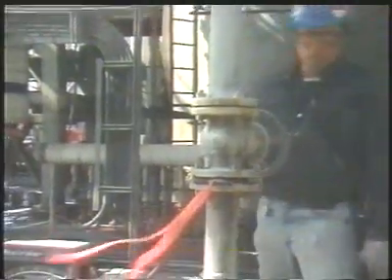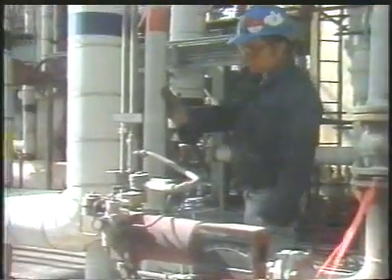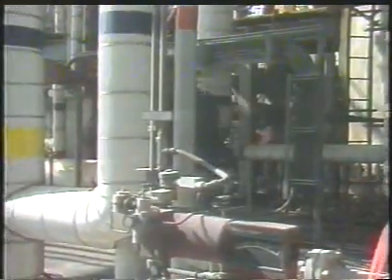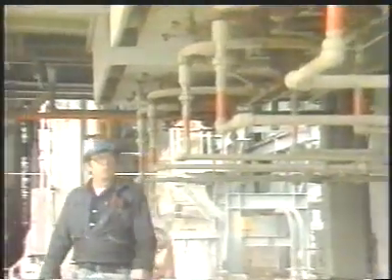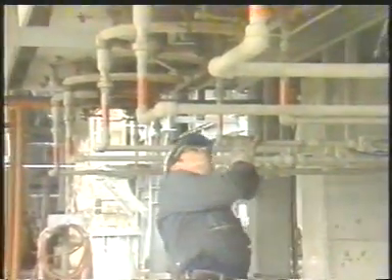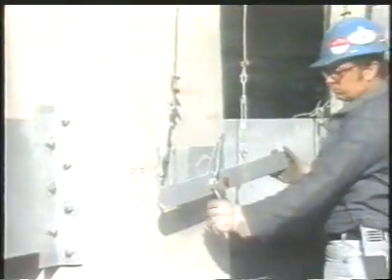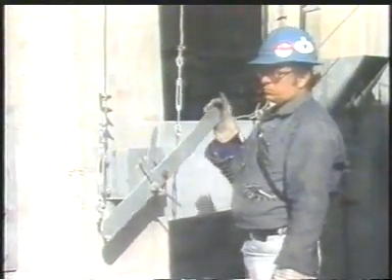The first step in the pre-startup inspection is to check that the pilot and main fuel systems are blinded and that the fuel supply for each burner is closed. Then inspect the furnace to assure that it is ready for startup. This involves inspecting the furnace to make sure it's clear of debris, checking the burners, and making sure all the furnace doors are closed. The damper and burner air registers should be fully open during startup so that the furnace can be adequately purged with air or steam.